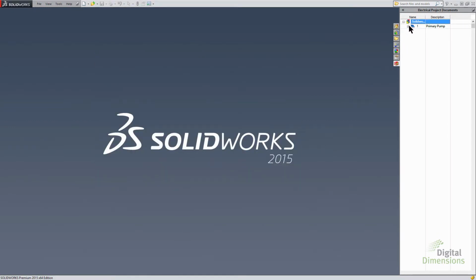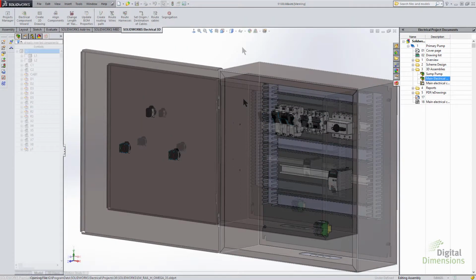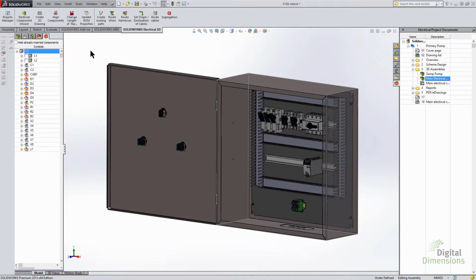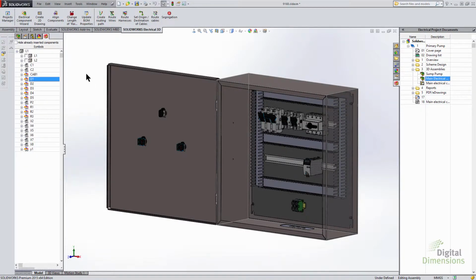And once again, we actually do get the library over on the right there. So we'll go and open one of them here, and then we'll go into the first item. Alright, so we get our components tree over on the left there. Notice the new icons there for the connectors. Also notice the infinity, or the lazy 8, there for permanent items that have been right-clicked and set as permanent, so that even if you delete the symbol on the schematic, they don't disappear from the project.